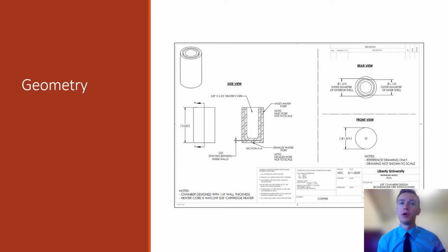So as you can see in the photo, there's a cylindrical core. That's where a cylindrical heater would go, that is surrounded by a copper sheath. And the little annulus that surrounds that is where the water would flow into and fully encapsulate the cylindrical heater in order to heat the fluid and vaporize it within this metal chamber to create the same sort of mechanism as a defense mechanism of the Bombardier Beetle, by increasing pressure by vaporizing a fluid within the chamber that will eventually be throttled out in hopes to replicate the same spray pattern of the Bombardier Beetle.